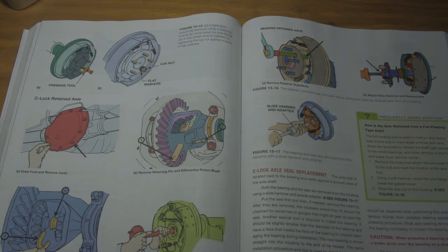Okay, now on to tear down and rebuilding of a differential. This part's going to be a little difficult for me to explain, so I'm going to hit on some specific topics, and then I'm going to have you guys watch the videos, because the videos that I have are done with actual components. But something to keep in mind, anytime you tear down an axle, before you just blow the whole thing up into little tiny pieces on your bench, you want to be mindful of finding the smoking gun. What I mean by that is something is obviously broken, and that's why you're tearing down the axle. It's always a good idea to take a report as you're tearing down a component and actually do a disassembly inspection procedure. It's not 100% necessary, but it does give you some peace of mind.